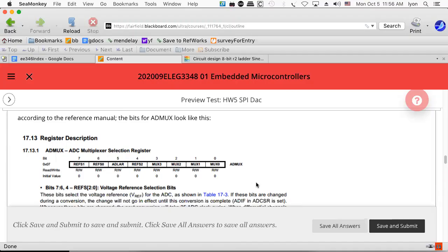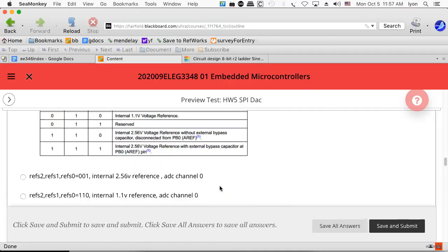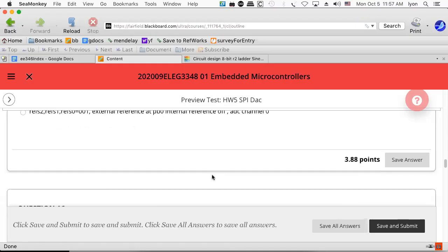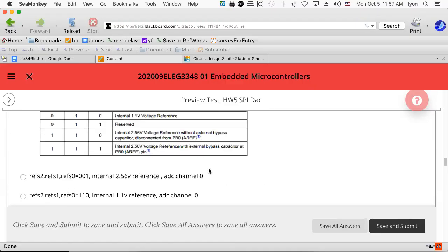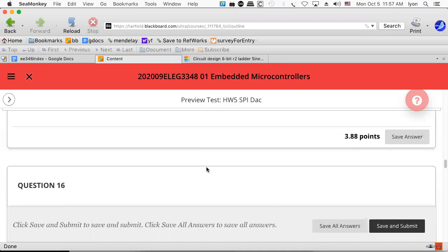And you're like, what the heck is that? What does that mean? And the answer is somebody didn't document what the ADC MUX selection register does in terms of its bits within the code. And often that won't happen because it's cumbersome to document all of this stuff. You need pictures. And so that's where you have to actually read the book and learn how to use the hardware. If there's anything this course tells you, it's that you can't program hardware unless you read the data sheets. And that's just the way it is with hardware.